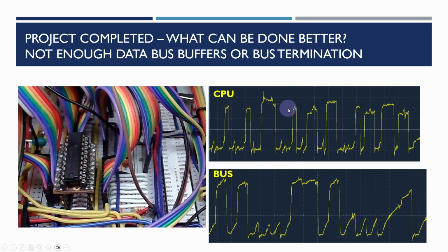The data on the top here is from a completely different time period from the data on the bottom, so not from the same time. Perhaps if I got the 2 probes, we could show the comparison, but it does indicate that perhaps there might be some issues here. And you can see down the bottom here in particular that there's not very much interference. It's certainly well below the sort of 2.2 volt high level, but along here it's probably getting a little higher, and this bit here and the slope here might indicate that there could be some potential problems there.